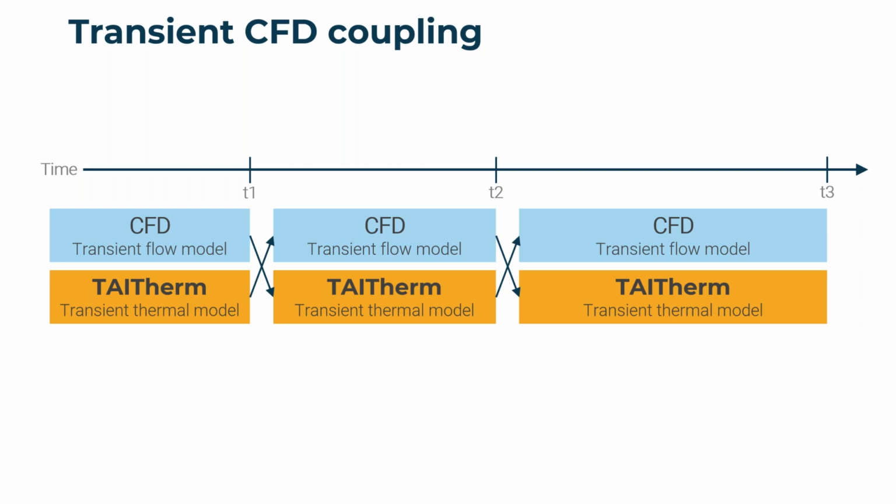in the thermal field. But regardless, we're marching both codes forward in time and then defining these exchange intervals where we map thermal and convective boundary conditions between the two codes and continue marching forward. So we can get good convergence of the co-simulation by controlling exactly how fine or how large that interval is for the coupling data exchange.